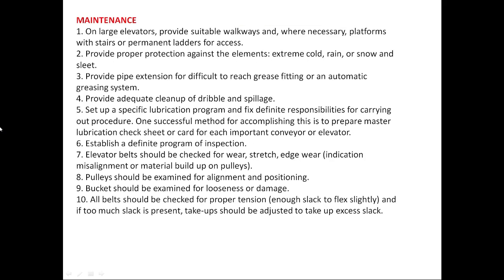If you see the maintenance view, large elevators provide suitable walkways and, where necessary, platforms, stairs or permanent ladders for access. Provide proper protection against the elements, extreme cold, rain or snow and sleet, and provide pipe extension of a difficult to reach grease fitting or automatic greasing system.